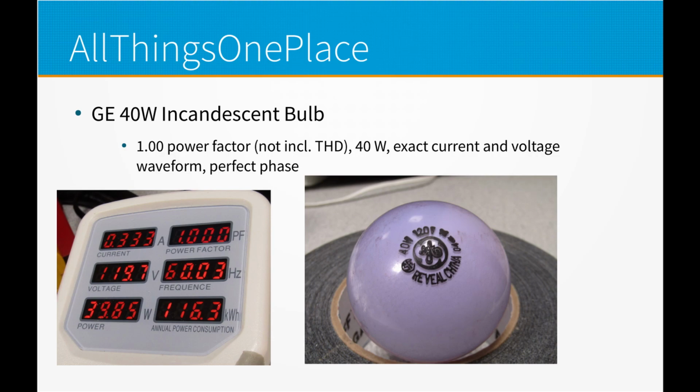All right, the next one, we got an incandescent bulb. Does anybody still use these? Leave a comment down below if you do. 1.00 power factor, basically perfect. Perfect phase. The current and the voltage look exactly the same.